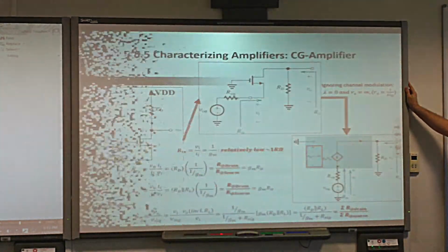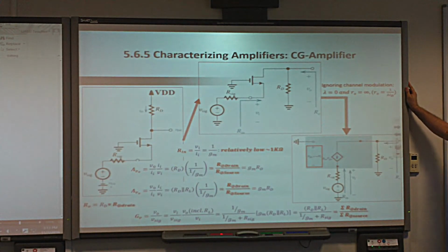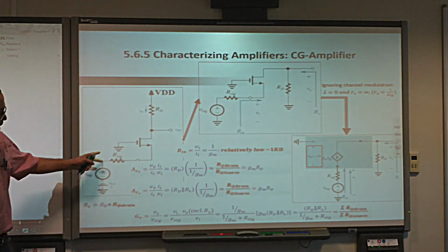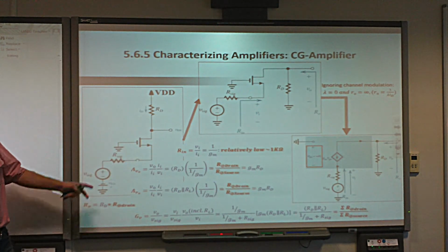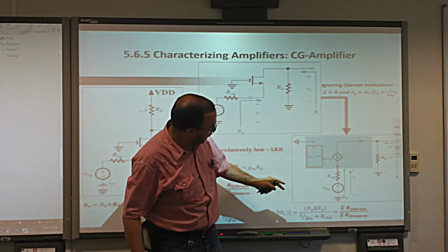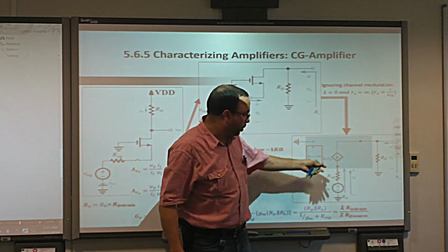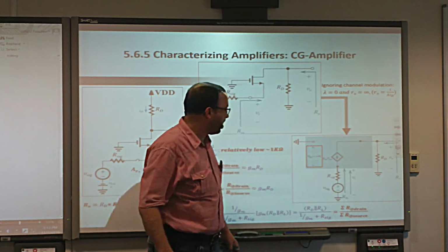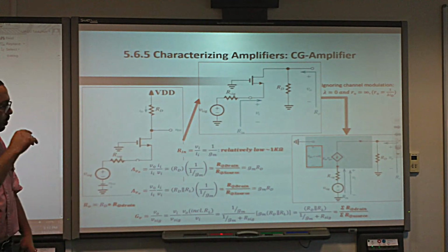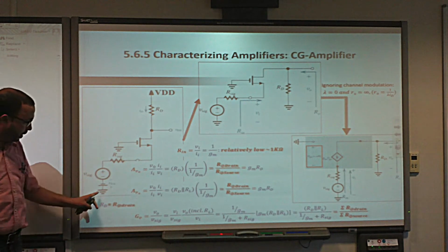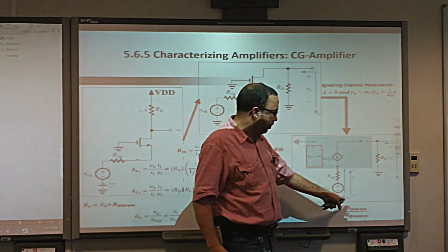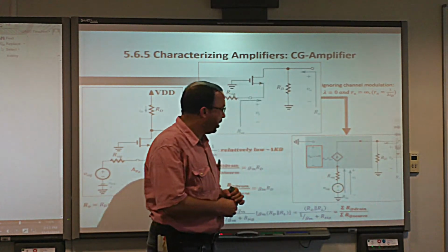And we finish today's class with this topic. It is about the common gate amplifier. It's extremely simple. So this is the circuit. In DC, we have to change it to AC. And again here, we use the pi model, but we could also use the T model, whichever is easy for us. And again, we took away R0. You can include R0 as well later on, but don't worry. Now the input signal is coming into the source and goes out from the drain. That's it. So this is the input, and the output is from the drain.